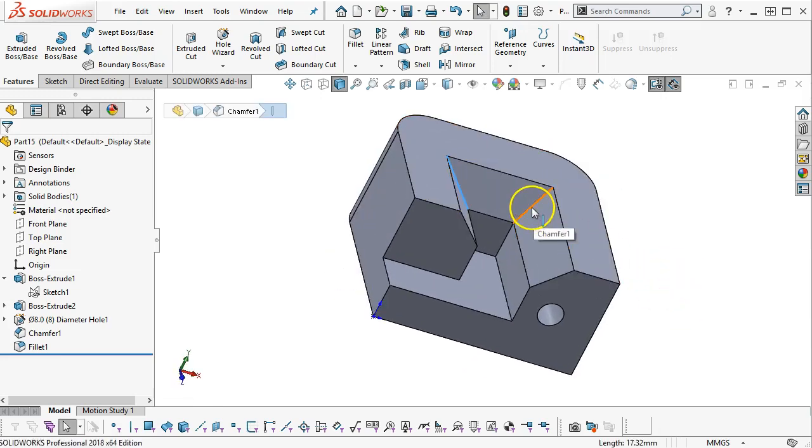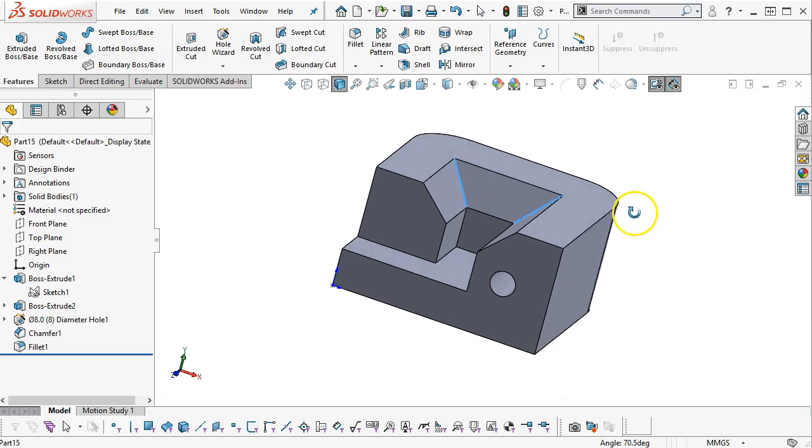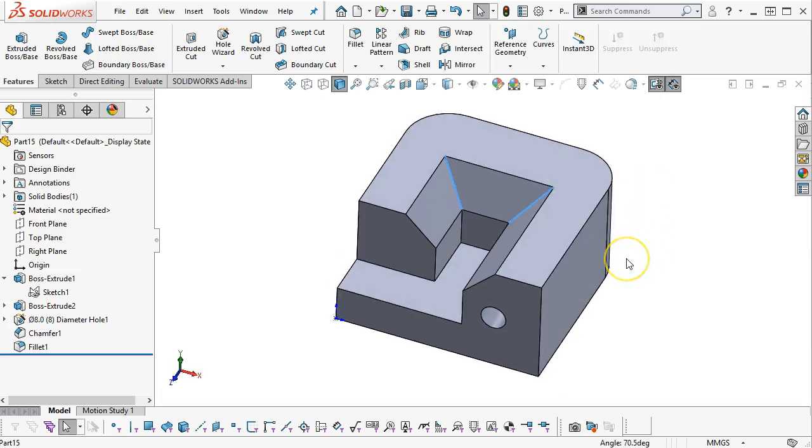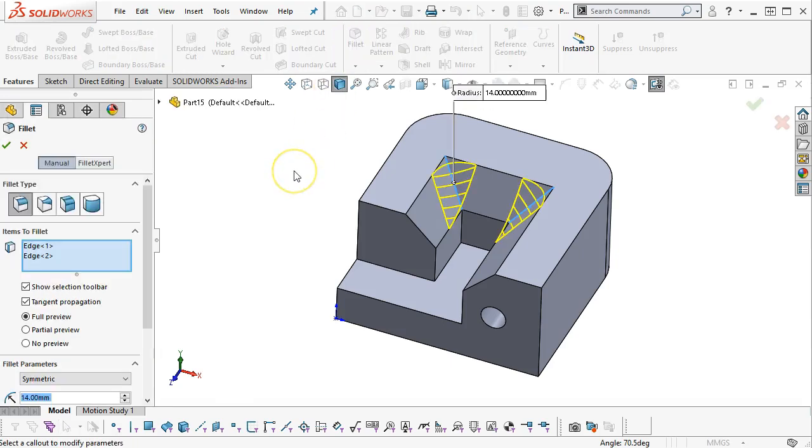I would have to sink or EDM to get that geometry in, or generate a 3-axis toolpath. A large, let's see, a large 3/4 inch 90-degree countersink drill mill tool might be able to get in there, but I would need a fillet to match.